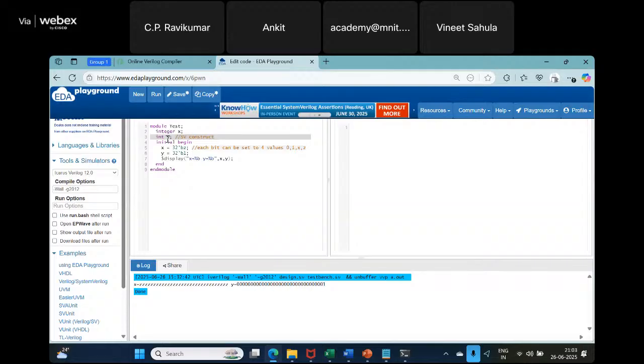You don't expect any x's and z's. So you have to use it carefully. If by chance you are actually going to get x's and z's, then this will happily print zeros, and you will think that everything is working. You understood, no? This can be a serious bug problem.